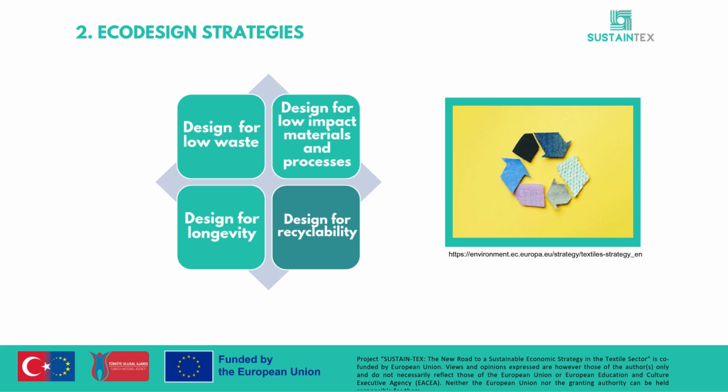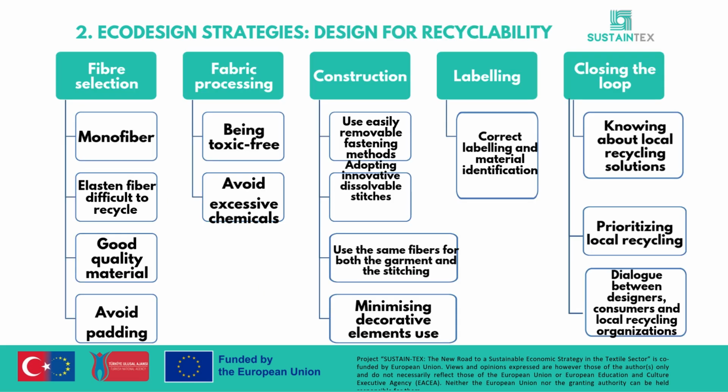Design for recyclability. Recyclability is greatly influenced by the way garments are designed. It is important to work with single-fiber fabrics, or as few different fibers as possible, to facilitate disassembly. Avoid fibers that are difficult to recycle, such as elastane. It is critical to choose materials of the highest quality from the outset so that the fibers will withstand multiple processing cycles. Avoid structures that are difficult to recycle, such as padding.